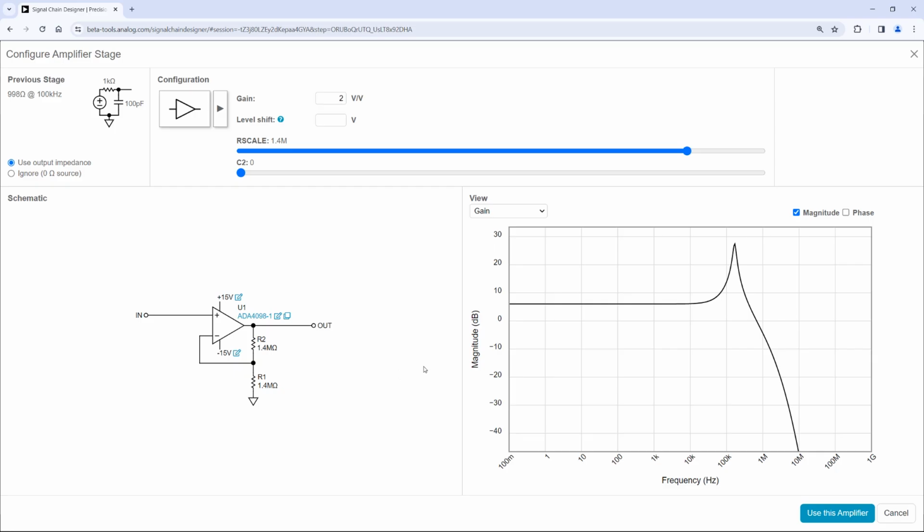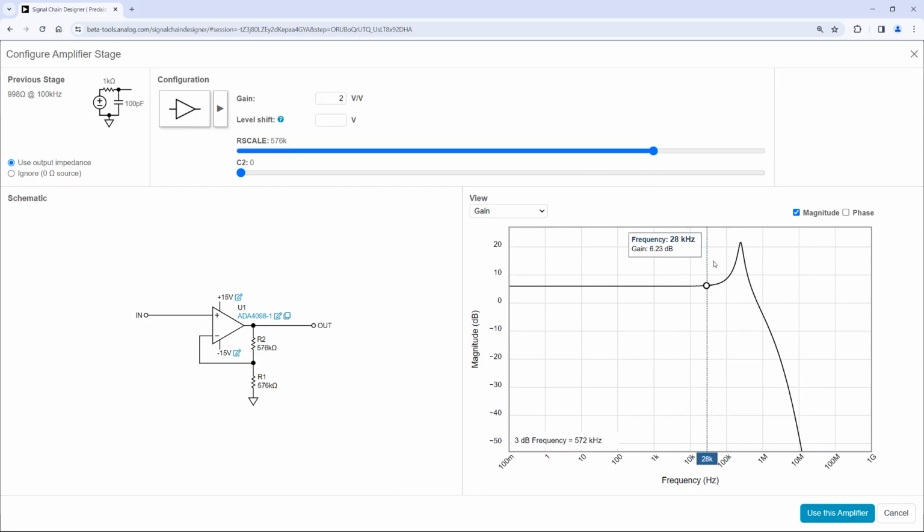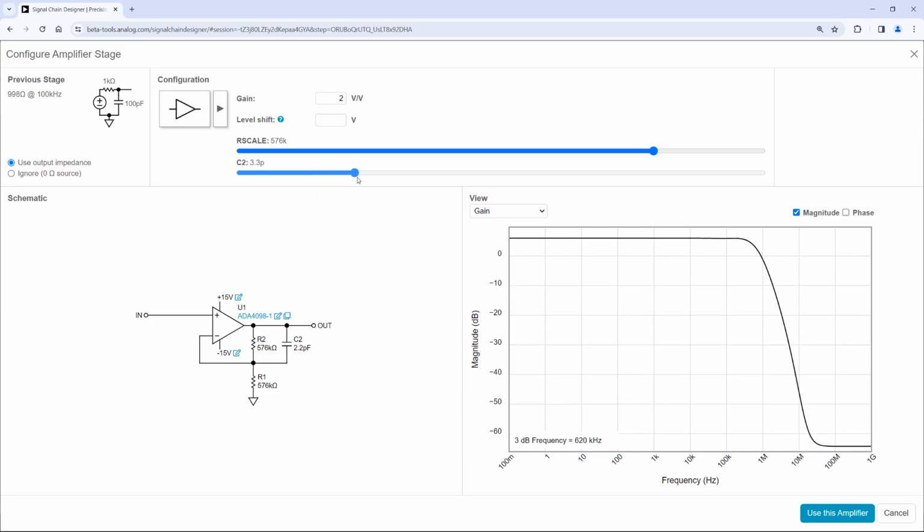There are a few things that you can do to avoid having this peaking. One is obviously to just use lower value resistors. If you want to use bigger value resistors, you can put a capacitance in parallel with that feedback resistor. Typically it doesn't require that much capacitance, and that'll knock that down. Now, instead of driving that at high frequencies, you can drive that capacitance directly through this capacitor rather than going through this resistor, and that stops that low-pass filter action.